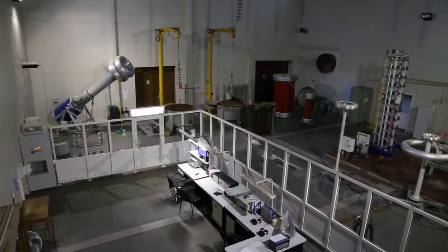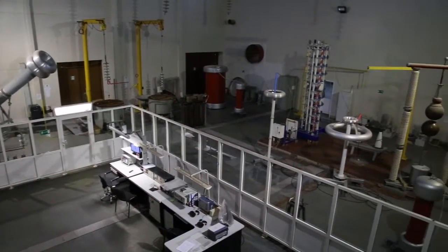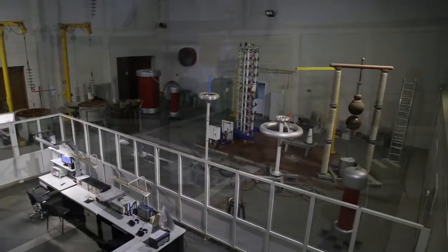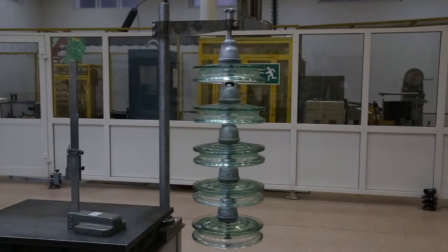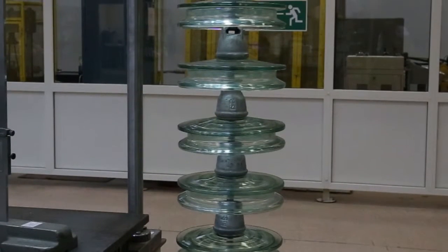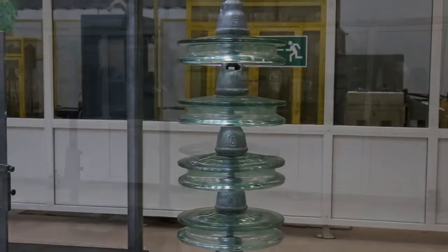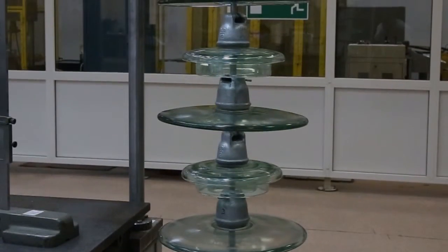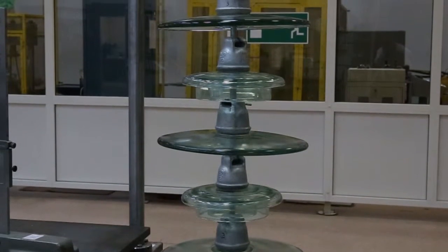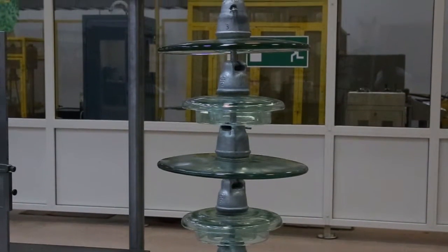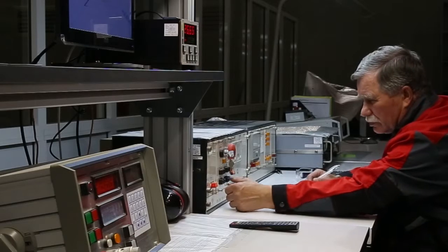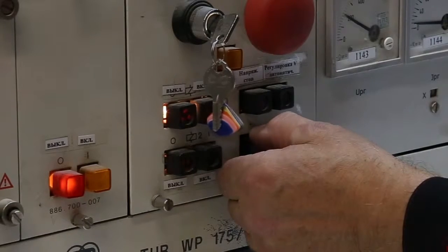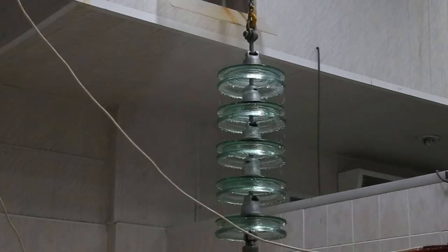GIG Operation Division from Global Insulator Group compared the following string units. One type string unit of 5 insulators of PSD70E type, 2-winged insulator. Mixed type string unit of 5 insulators of aerodynamic profile U120AD and U70BL. Insulators were tested in accordance with the power frequency wet withstand voltage test.